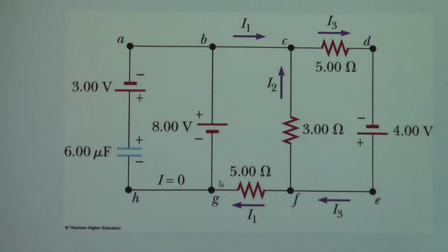Okay? But here's really that first key step. I'll say it again. What do we know about this capacitor? It has built up enough charge until what current is over here? 0. And I guess the diagram here gives it away here. After a long period of time, that current is 0.